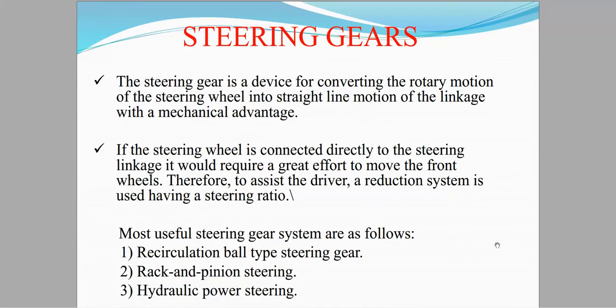Let's discuss the steering gears. The steering gear is a device for converting the rotary motion of the steering wheel into a straight line motion of the linkage with a mechanical advantage. If the steering wheel were connected directly to the steering linkage, it would require a great effort to move the front wheel. Therefore, to assist the driver, a reduction system is used, having a steering ratio.